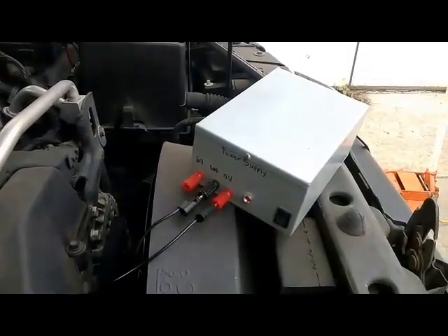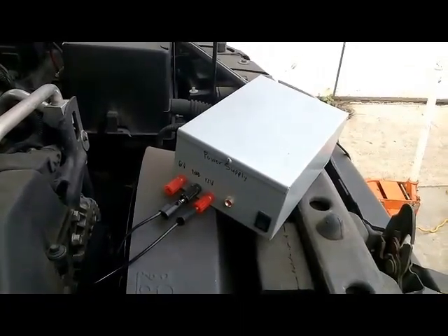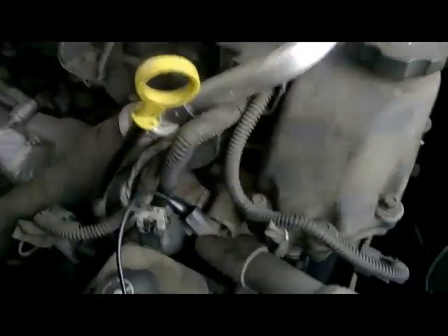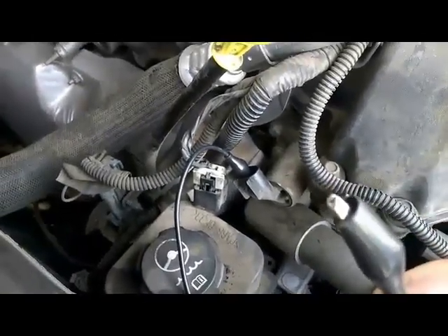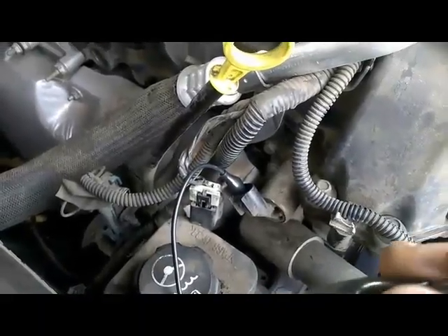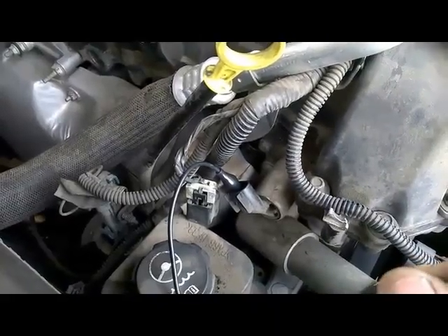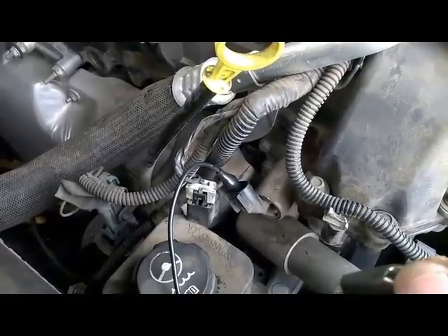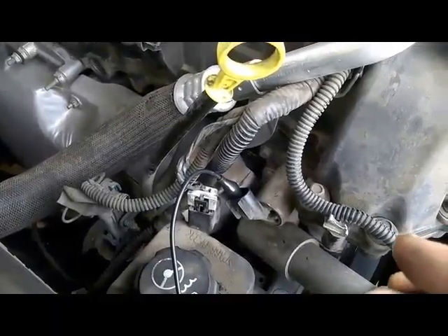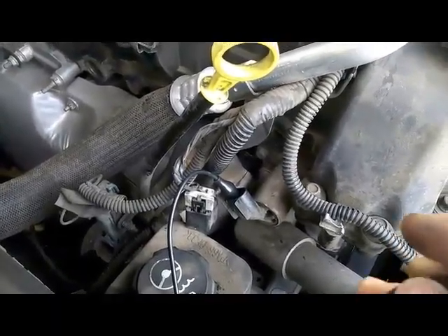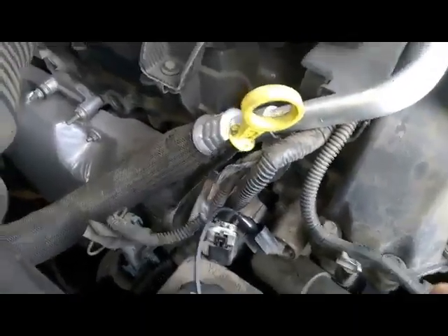So I already have my power supply hooked up. It's a 12-volt power supply and also a 6-volt. I have my leads already back probing one terminal, and I have the other terminal right here. I'm going to touch the last terminal on and off, and if our solenoid clicks, it means that the mechanical part of the solenoid is functioning. It means that our coils are intact, and also our pintle inside the solenoid is able to function. All right, guys. So this is with the engine off.